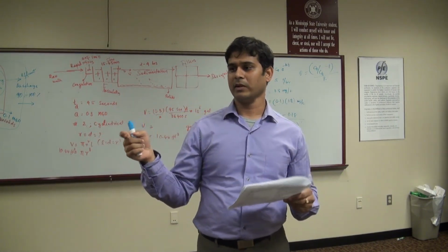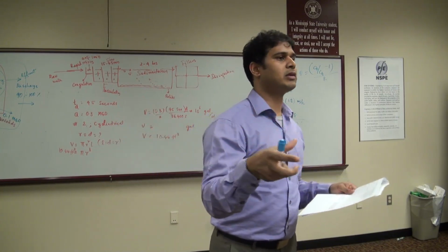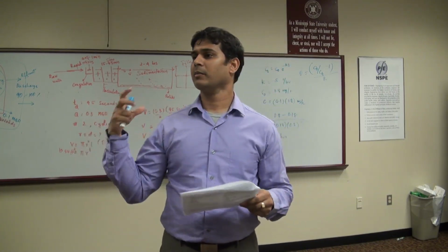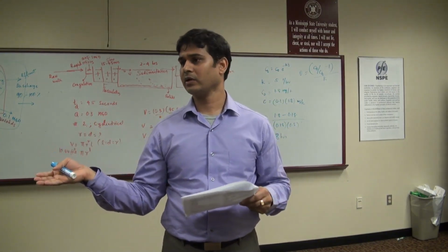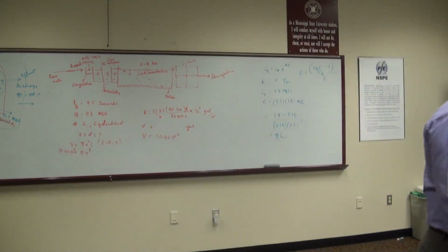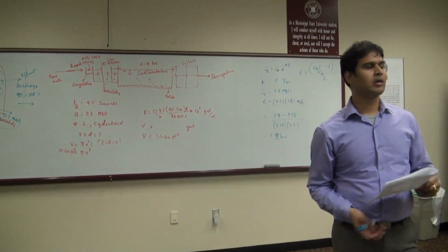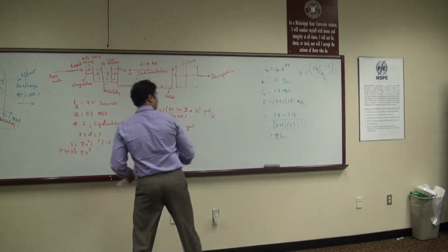Multiply with the equivalent weight, right? Actually, you divide by equivalent weight, because once you get equivalents, you multiply with the multiply factor 50. That gives you milligrams per liter as CaCO3. Milligrams per liter as CaCO3. Do you remember that? So the equivalent weight would be how much?